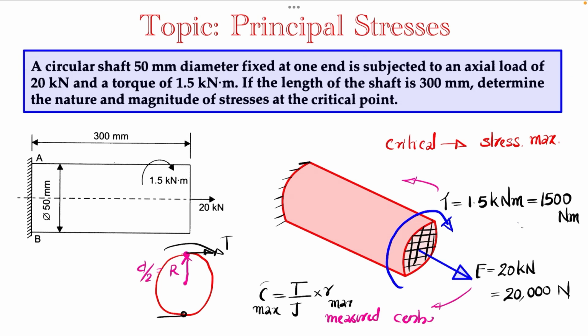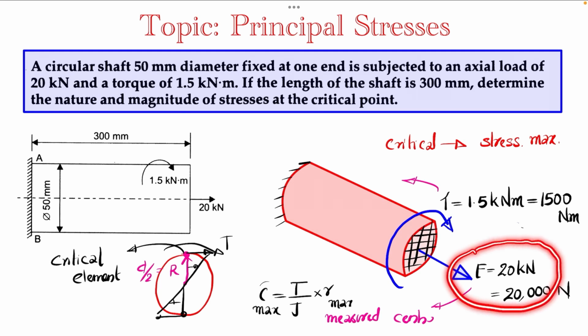The distribution, you have already studied. The distribution will be like this. So this point, which lies at the outer surface element of the shaft, is known as the critical element. And here the torque applied will be transmitted uniformly throughout all the sections. So corresponding to load, all sections are critical, and for the axial normal stress, all points can be taken as critical.